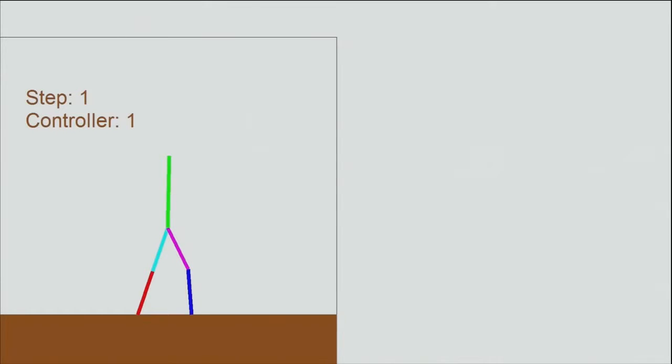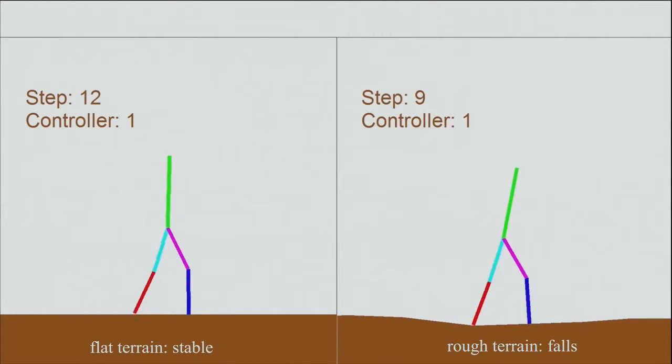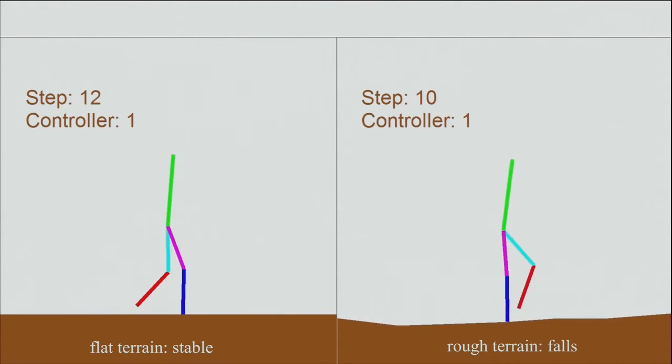The approach we're going to use is to design these low-level controllers. Here's an example of one controller. Intuitively, what it's doing is it's got a torso that's biasing it to walk forward just a little bit to recover energy, and it's lifting its feet nicely on terrain. It has a stable limit cycle when it's on flat ground. And if we move it over to rough terrain, it'll walk for a while. But especially when it's going uphill, eventually this thing is going to trip.